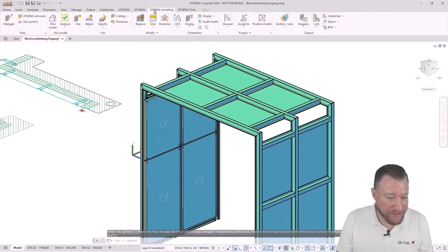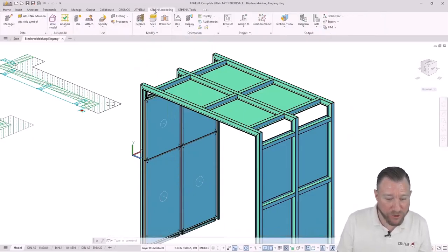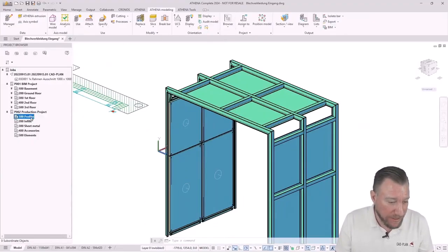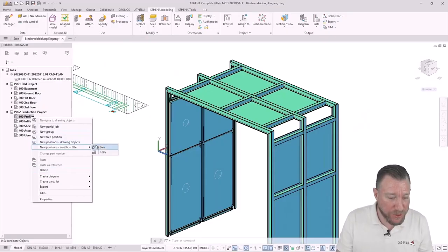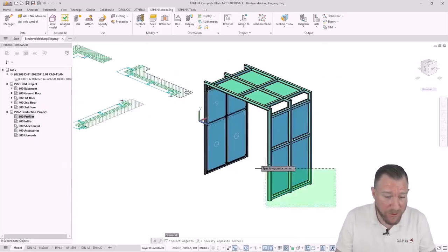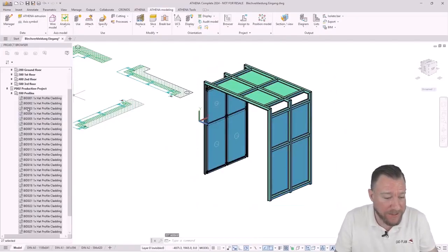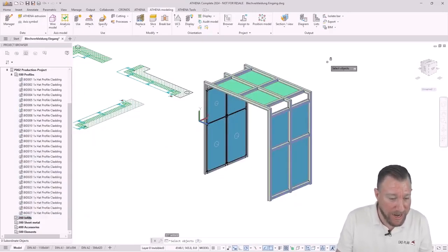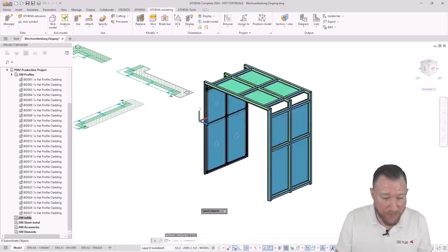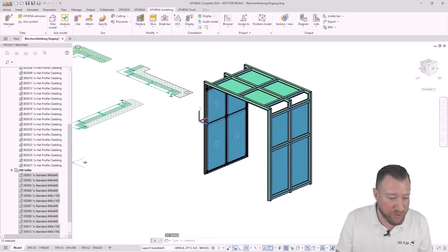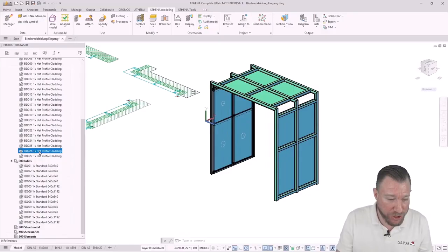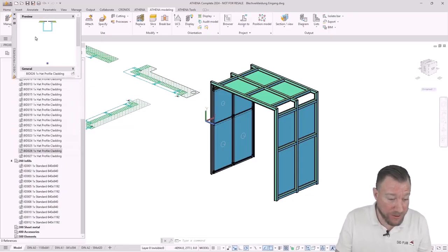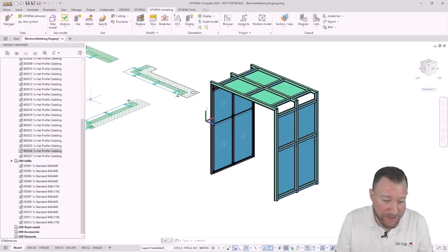So I hide the parts again using the AutoCAD layer control, and now I show you the complete evaluation of the model. You not only want to simply create a 3D model, but also to be able to evaluate all parts up to export to the processing or manufacturing machine. And for this we use the ATHENA project browser to position the substructure, profiles and the sheet metal panels. This gives you a complete overview of the construction, for example, the individual parts.